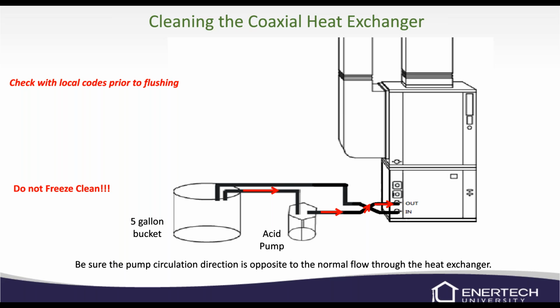I know that back in the day, we had some old Econar equipment and we acquired them, but I know Econar used to do some freeze cleaning, and we don't recommend freeze cleaning. Too many things can go wrong, and if you bust a heat exchanger, it's never a good thing. So don't freeze clean, just use some CLR, some muriatic acid, or some bleach, or whatever you feel.